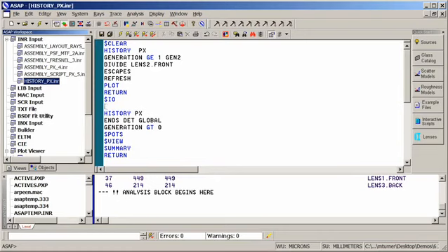This first set of commands is for the previous example where we looked at the Fresnel reflections off the front surface of the second optical component. What we want to look at now is all of the rays that ended on the detector that were not of the original ray bundle. So I've eliminated the 0th generation, and we're going to look at the rays that otherwise end on the detector. But rather than looking at the rays, we're going to look at the spot information. Where are the rays on the surface? We could also look at some summary statistics as well.